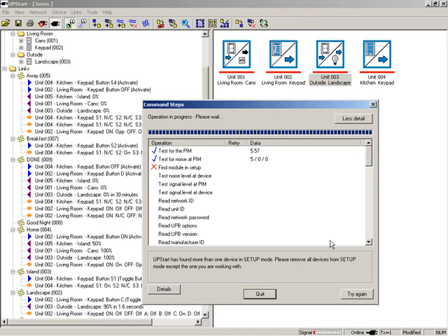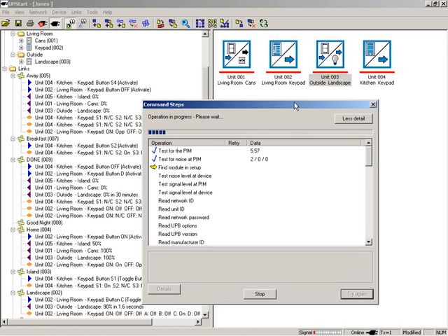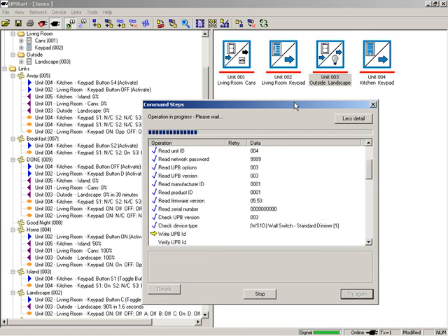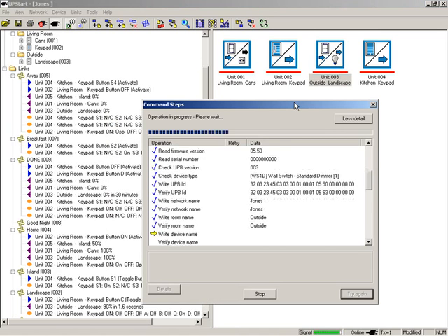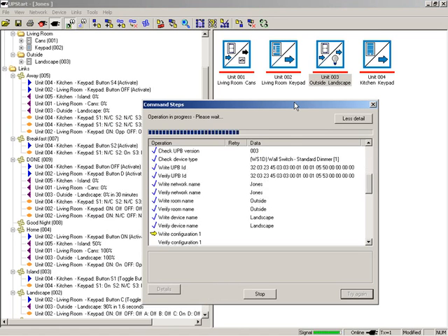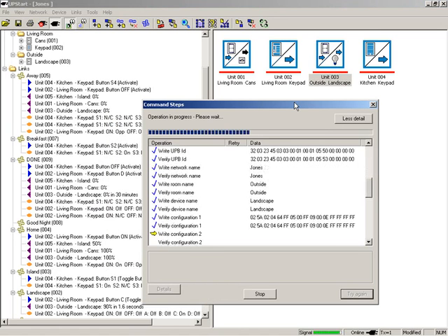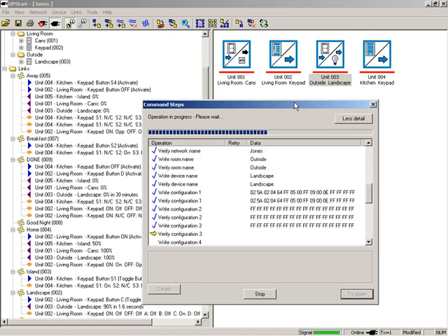And that's one of the things: if you add a device offline, like I did, and I made it the wrong kind versus what it is, it's going to tell me, hey, you're wrong. It's a wall switch relay, not a dimmer module. So be careful when you pick what kind, whether you're using a WS1D or a WS1DL, an LED device, versus each other. Now, to program a device, it does take about a minute to download to each unit. So plan on that in your programming time.